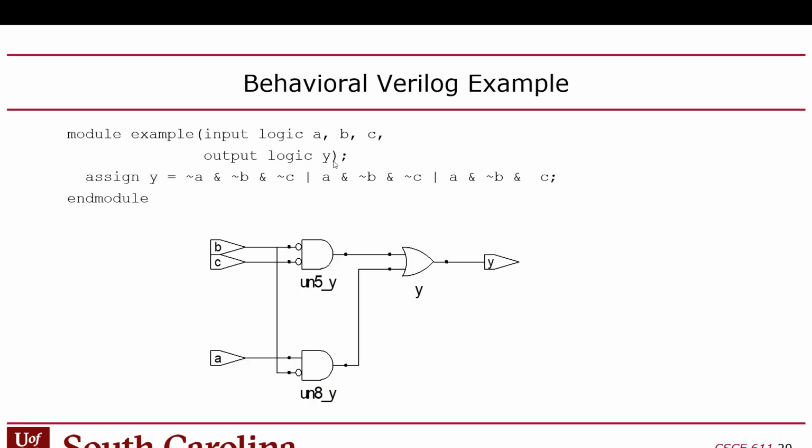Okay, so then as I mentioned, the tool actually, if you take this code, now this is behavioral code, and you'll notice that if you run it through the synthesizer, it'll actually show you the corresponding structural code, in which it actually allocates gates.